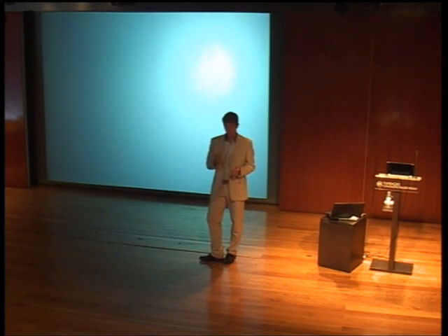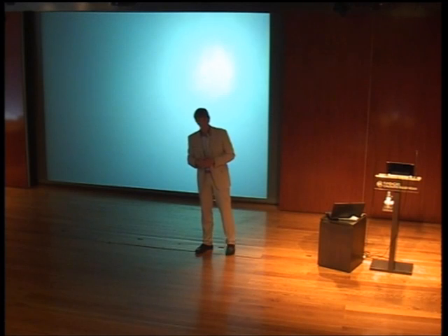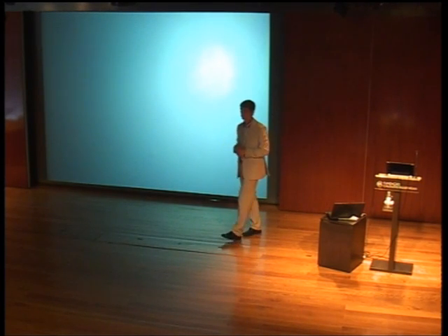Sure. So you can also do it with 1 if you want, but then there will be lots of information you will miss. For a spray, I don't really recommend it because you have those tiny droplets. If you do this processing with only 1, you will miss a lot. But if you have a flame or a flow with a smooth curve, you could do the process with only 1 image and post-process. You lose image resolution, but you gain in optical setup. Another question? Thank you.